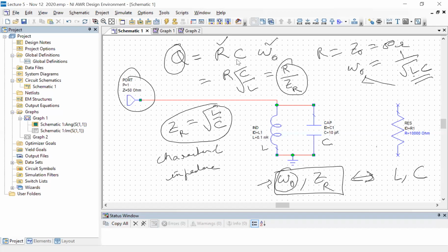So this is one way of changing the Q factor when you don't have an option to change the dissipation aspect of it. But this might not always be possible, because you can't arbitrarily change the capacitance and the inductance in any realistic circuit. I have mentioned a few times that typical values of these things at microwave frequencies are not so easy to make.